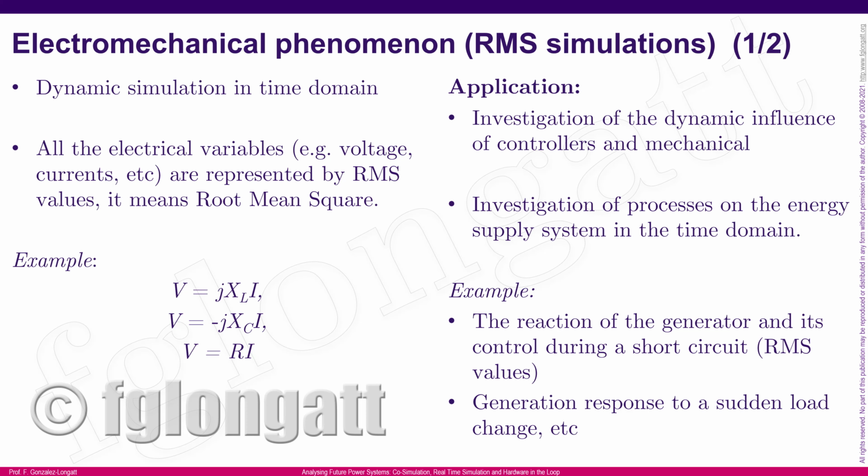We assume that the inductors and capacitors are represented by reactances, and from there, the use of the concept of impedance and phasors allows a very good solution. In this case, the dynamic that we are interested in is basically the dynamic related with the synchronous machine, controllers, and mechanical devices. The good news here is that we can use a larger time step integration that is computationally not so heavy as the EMT.